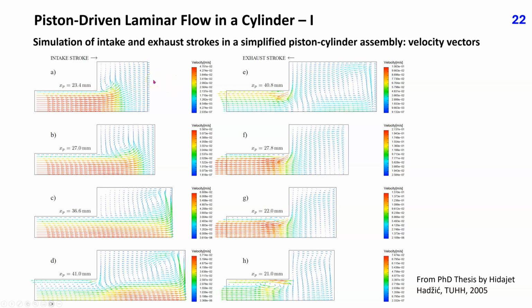In one simulation, equations written for moving control volumes involving the space conservation law are used and the grid topology is not changing. In another simulation, equations written for fixed control volumes are used and solutions from previous time steps are interpolated to centroids of control volumes at the new time level so that the local time derivative can be computed. In both cases, fully implicit time integration methods, implicit Euler or quadratic backward, are used.